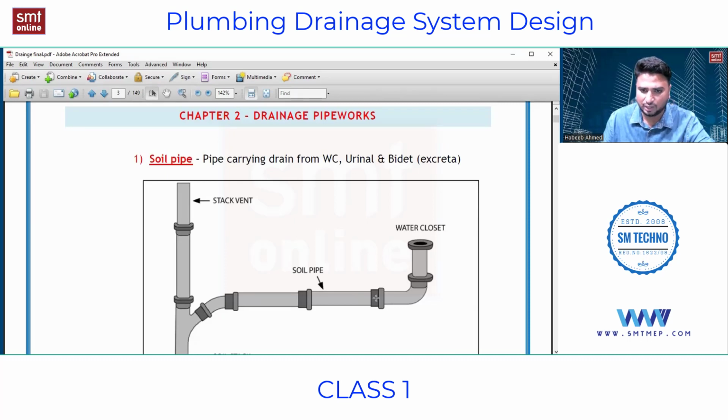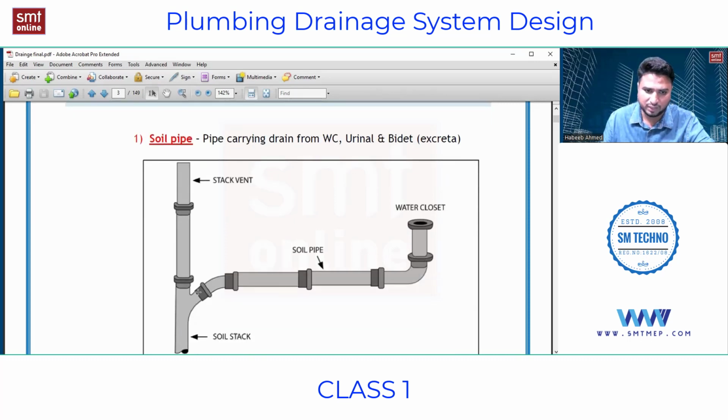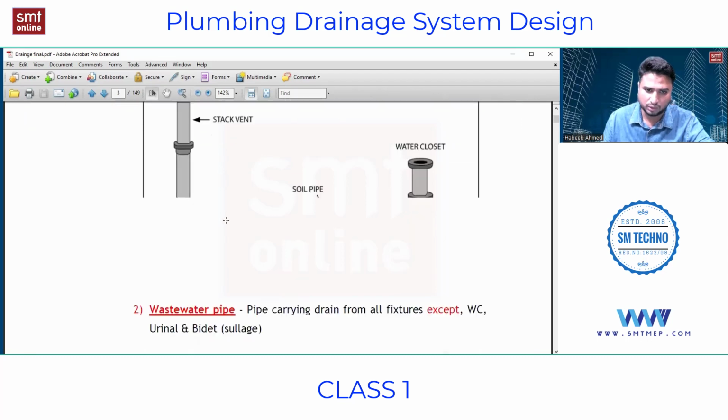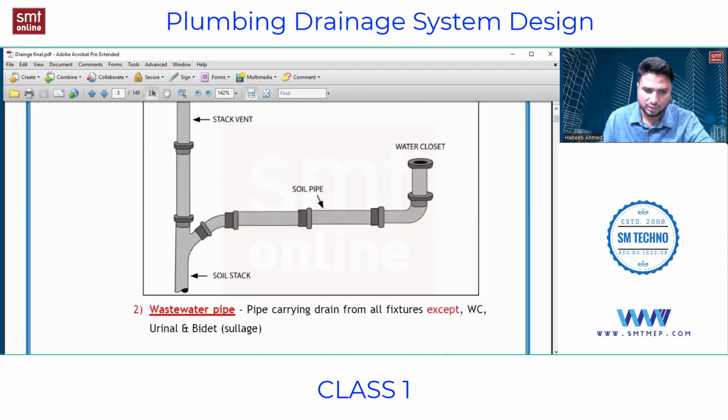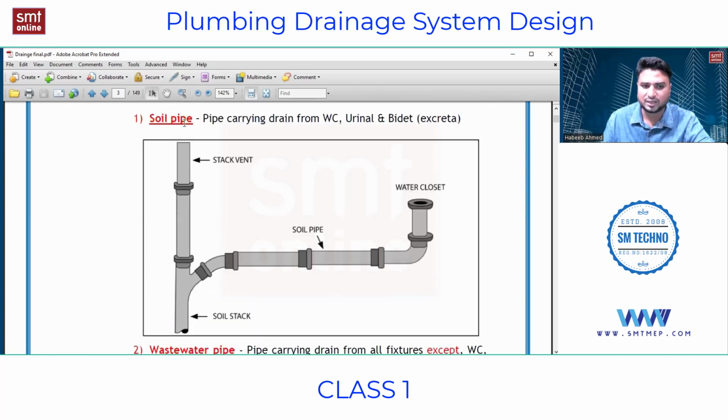This is carrying along the waste, and the human waste is collecting into this vertical pipe. This goes down by means of gravity, and the gases will rise above, okay, and it'll try to get disposed into the atmosphere.